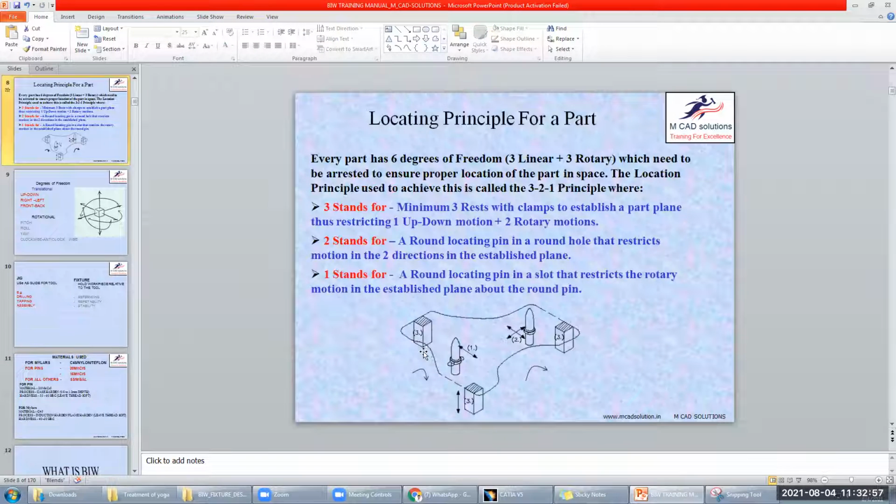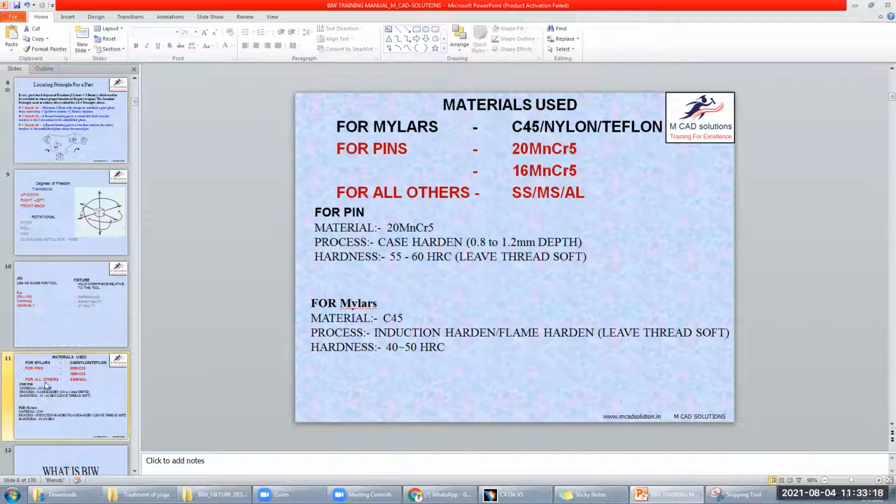In our case, where is the motion? We are clamping and resting this part. After completing the particular operation, this panel will be moved out and another panel will be kept here. So with continuous panels going out and in, this area will wear out. To avoid wear out, or rather to minimize it, we are using a higher carbon percentage.